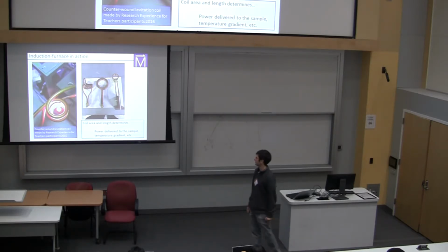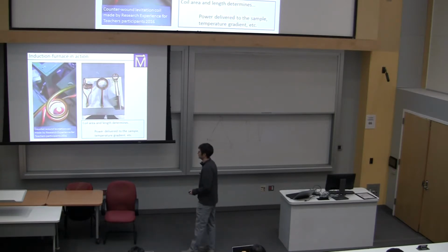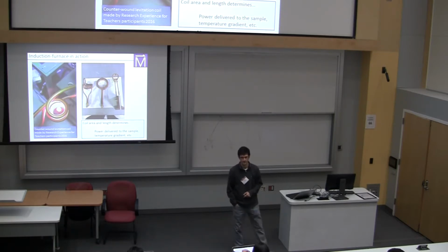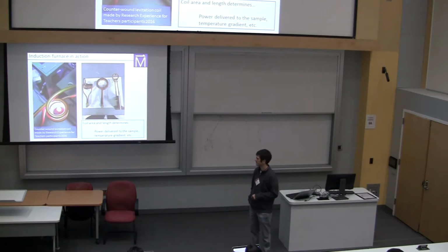Okay, so that's neat. The other thing that I want to emphasize is the very fast heating time. We went from room temperature up to maybe 1300 or something like that in tens of seconds. So it's a rapid throughput type of apparatus. You can also consider the utility of this in quenching specimens. You could easily set up something like this that has a quench bucket underneath it, and drop your sample out into that. So that's a nice thing to be able to do.